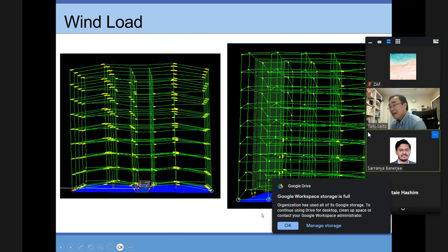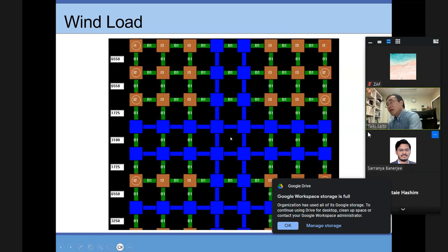Yes, sensei. So in the basement, I mean, you assume 2D rigid. Yes, sensei, we can do that. I was also thinking about that. You can put 3D rigid for this. Okay, yes, sensei. Then the whole slab will move together. No. Even vertically, it moves together. Yes, sensei. Okay, sensei, I will try with that.